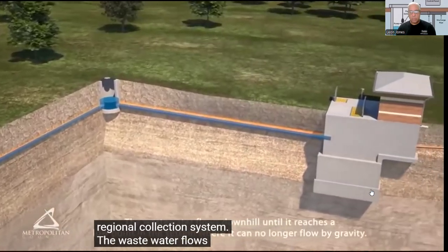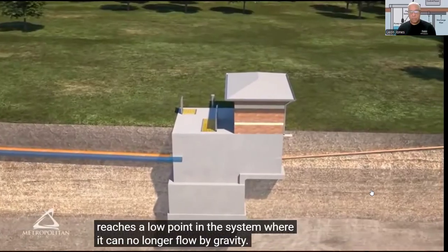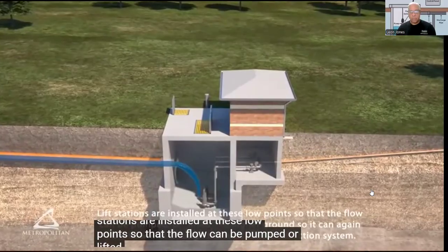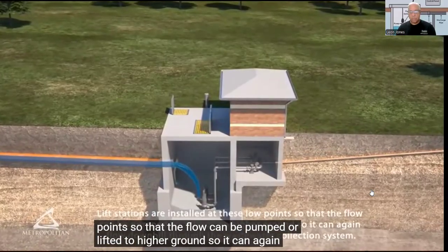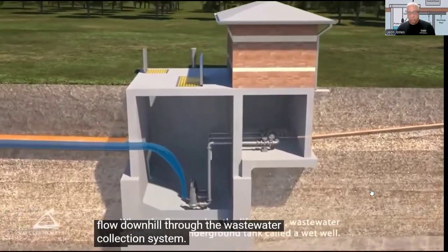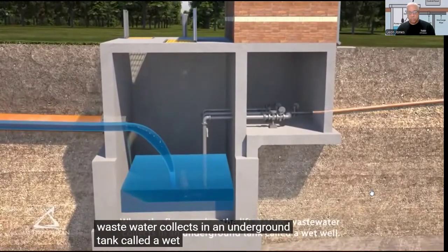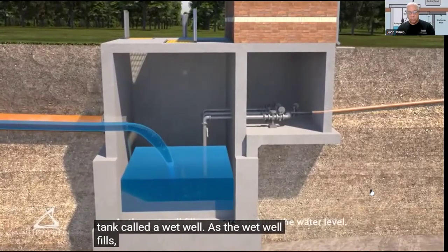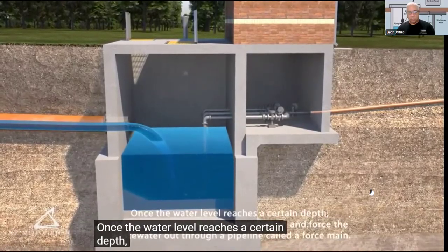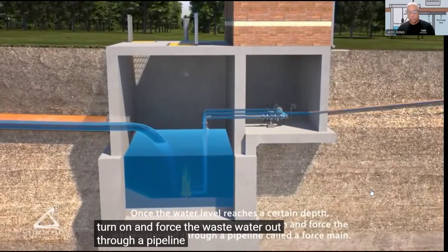The wastewater flows downhill until it reaches a low point in the system where it can no longer flow by gravity. Lift stations are installed at these low points so that the flow can be pumped or lifted to higher ground so it can again flow downhill through the wastewater collection system. When the flow reaches the lift station, wastewater collects in an underground tank called a wet well. As the wet well fills, sensors measure the water level. Once the water level reaches a certain depth, the pumps inside the lift station turn on and force the wastewater out through a pipeline called a force main.